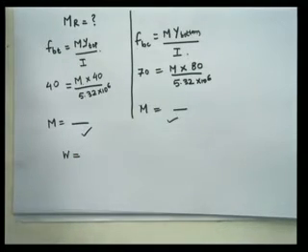Now if the cantilever beam is there, we are basically taking it as what? We are taking it as compression at the bottom and tension at the top. But if it is a simply supported beam, we are taking the compression at the top and tension at the bottom. So now in this particular case, when it is an overhanging beam, what we have to do? We have to take the top as compression, and the bottom we will take as tension. How we will decide that?